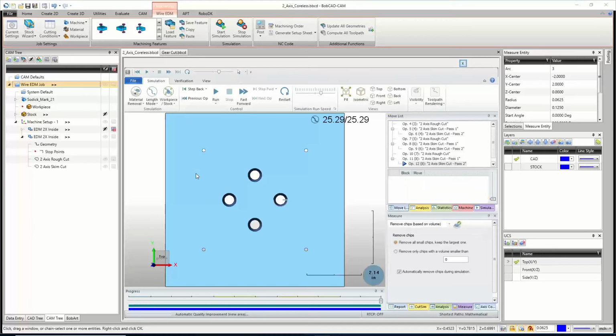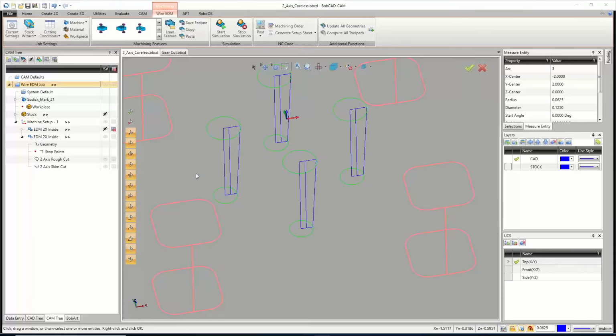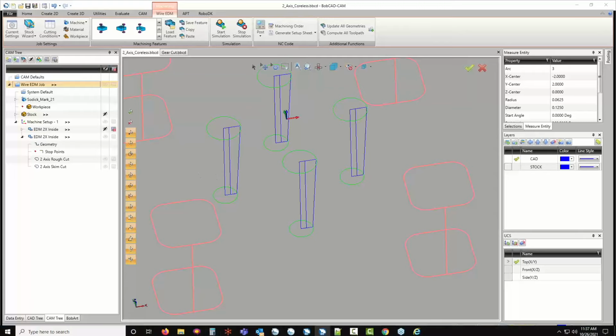All right, if anyone has any questions, feel free to throw them in. I'm going to open up kind of a goofy example that I have, but it allows me to show you guys some 4-axis real quick, because a lot of times with not land and taper, but tapered, even 2-axis, depending on how your parts show up, sometimes you get better control if you actually run them as a 4-axis shape. So I'm just going to open up, I got a part file here.